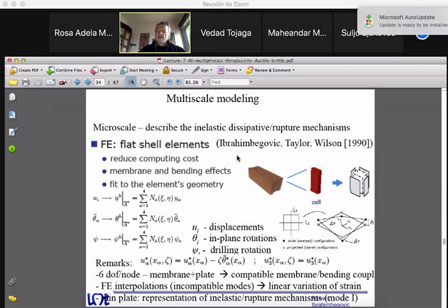So all kinds of interpolation have to be defined, namely for a displacement field and rotation field. Of course, you have to devise the corresponding interpolation for these shells in terms of displacement and rotation. There's also the plate bending rotation. This is a drilling rotation, which is perpendicular to the plate of this shell. So basically, this has to be developed very carefully, because you have all kinds of locking phenomena in plates and shells. I didn't talk about that. This is another course, really the full thing to talk about structures. Basically, you need incompatible modes and all kinds of stuff to handle this.